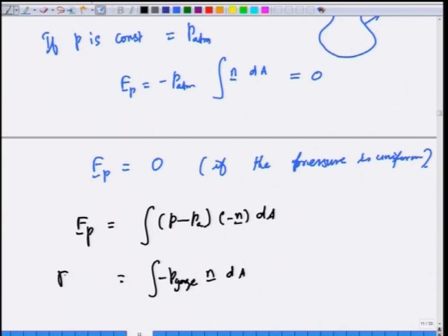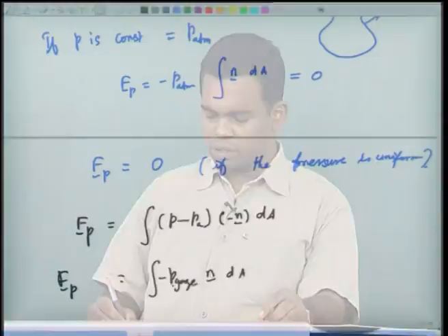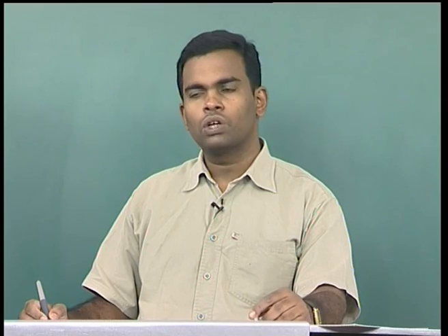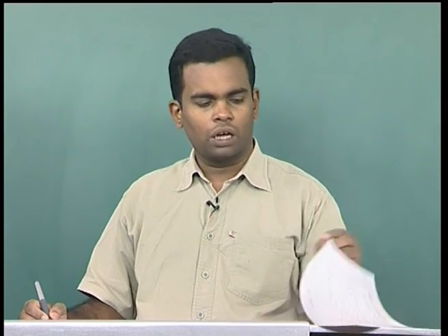So the net pressure force is really because of the difference between the pressure and the atmospheric pressure. If the only pressure is atmospheric pressure, it is completely uniform, so it will give rise to 0. So the gauge pressure comes naturally when you want to compute the net pressure force contribution on any control surface in a given problem in momentum balance.